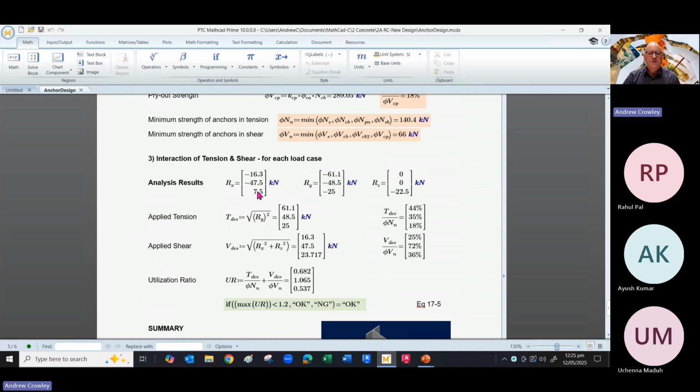So we've derived these arrays from our matrix, which was basically the table above, to give us our Rx, Ry, and Rz. And remember, Multiframe talks about linear forces in terms of Rx, Ry, and Rz. In our case, Ry is upwards, and for these load cases, everything's in tension, because when you were designing that anchor, we're really looking at the tension cases.